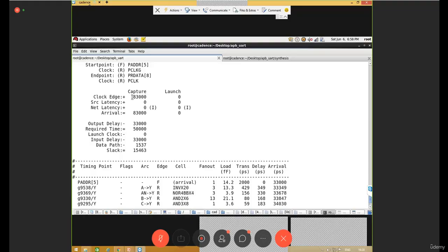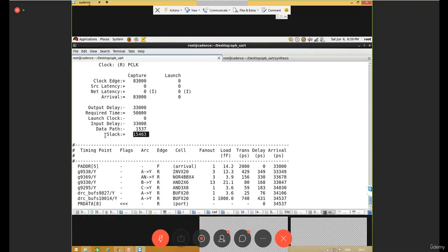This is how we analyze whether a 33 value is suitable, or that 83 value is suitable. If my slack is positive or 0, then whatever values you have mentioned in your SDC file are suitable for the execution of this process. So, is it clear how we get to know it is a perfect value?